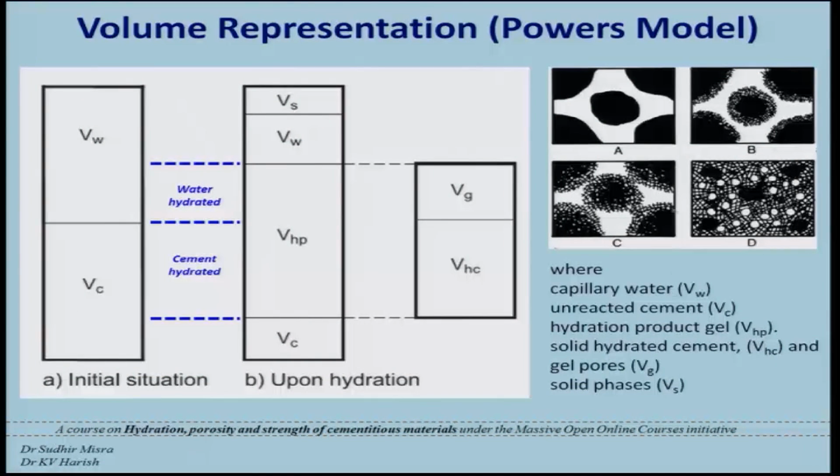Now, coming to Powers' volume representation and how to understand it. Two cases are given: one is the initial situation, the other is upon hydration. He gives a volumetric 2D representation where one portion is water and the other portion is cement, and remember that this is completely unreacted water and completely unreacted cement.